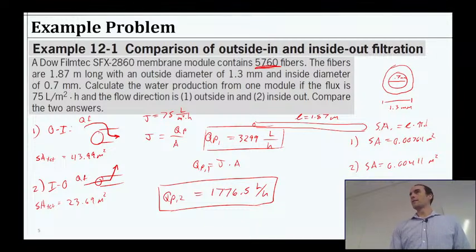All right, does that make sense though? Overall, the process for solving these membrane problems is never going to be ultra complicated for the level of stuff that we're going to do. They are inherently kind of simple because we don't have reactions happening. At the worst, they're fouling some, and the resistance changes, which might change our flux a little bit or change the pressure requirement. But it's relatively straightforward once you get a handle on where the pieces go and what the parameters mean.